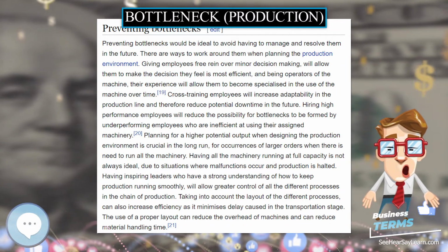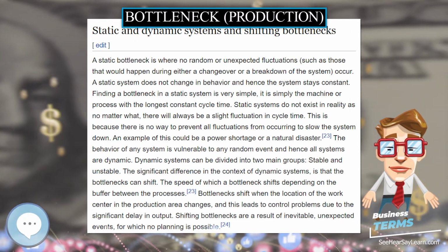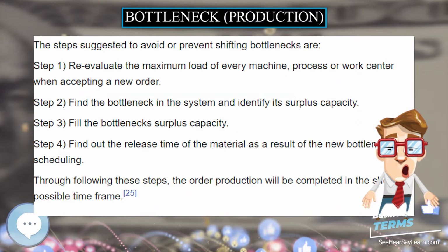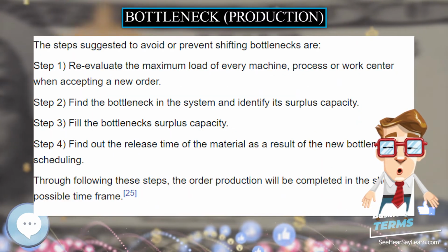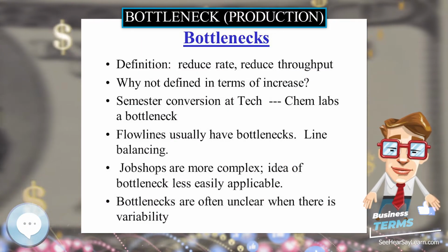Some means of doing so are adding resources to the bottleneck operation, more people, minimizing downtime, eliminating non-value activities, investing in more machinery which completes the same action, and optimizing the bottleneck's operation.